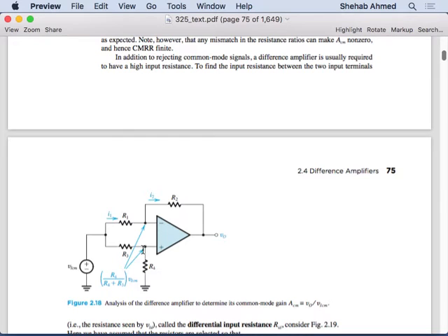So instead of the manufacturer telling you, okay, these are 10 kilo ohm resistors, plus minus 20%, which you'll get for cheap, if you want 10 kilo ohm resistors, plus minus 5%, they're the same resistors. He's not telling you something different. But what they're doing is passing them through tests. These tests cost money, so you pay more. You want 1% error, you pay more. 0.5% error, you pay more. But it's the same resistor. Right?